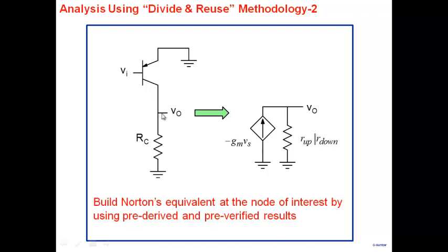One is, Norton's equivalent will require you to find Norton's current. So when you calculate Norton's current, remember you'll short this. When you short this, everything below this short disappears in your entire circuit. So a large part of the circuit no longer matters because you've taken this particular node and shorted it. It goes away.